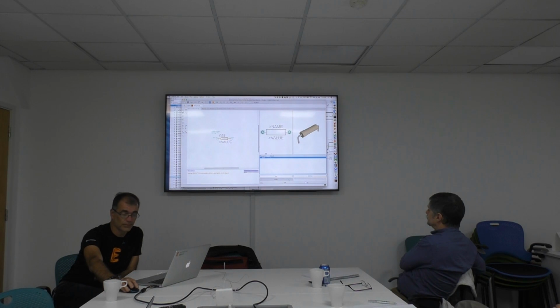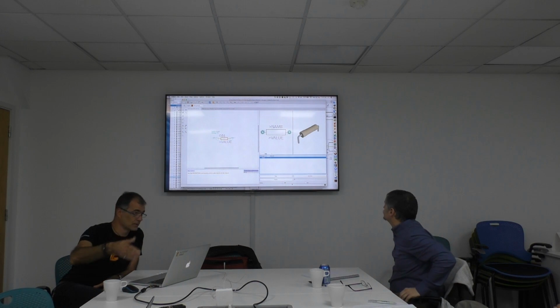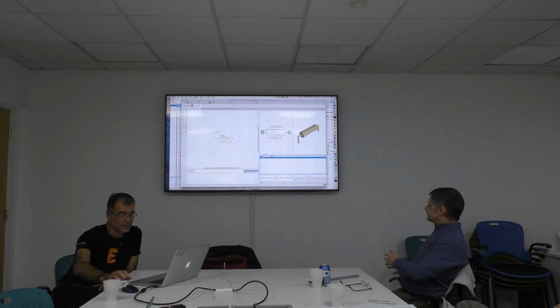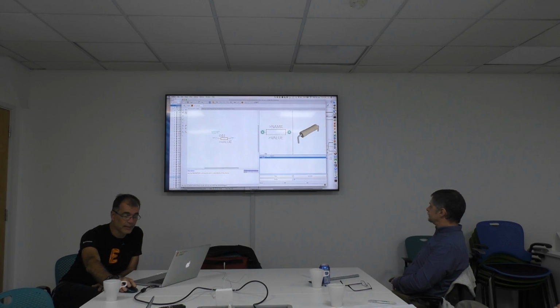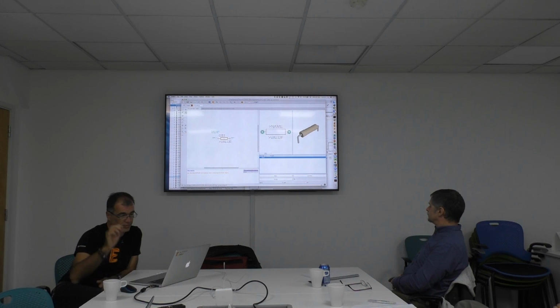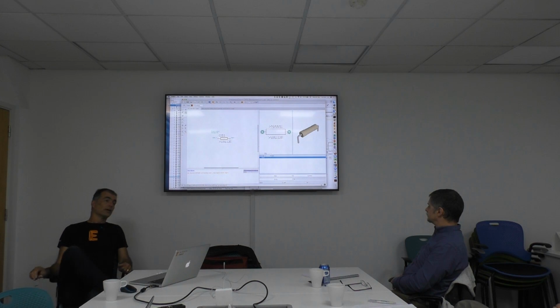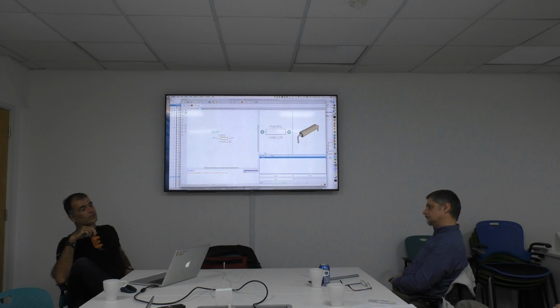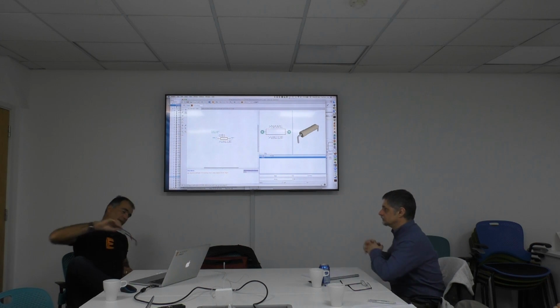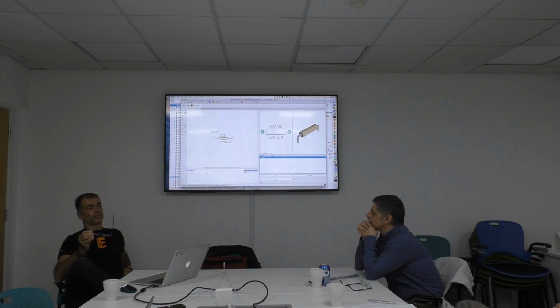Then next step, we typically have a prefix. Resistor R. So that's for the automatic enumeration, R1, R2, something like this. Diodes have D, or IC or U for an integrated circuit. So that's this one, and then I have here Value on or off. What does this mean? Value off means the value is not user definable. It's a bit crazy. You have to think around the value word that comes from behind. Value off means the user is not allowed to define a value.